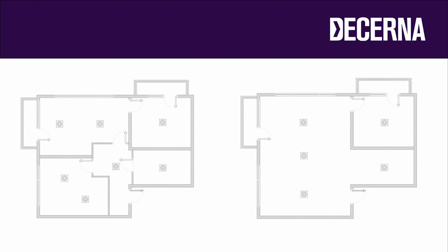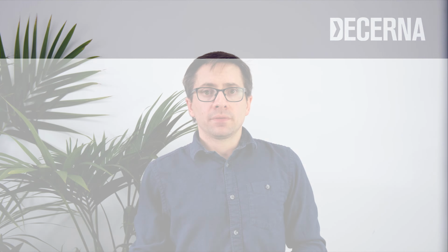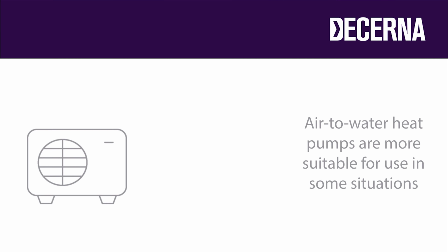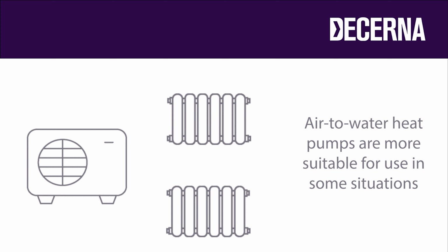Air-to-air heat pumps are usually best suited to sites with large, open-plan spaces, and the number of indoor units for a given floor area can be kept to a minimum. Although there is a high level of controllability from individual indoor units in each room, the costs can quickly mount up. The cost of an indoor heat pump unit is considerably higher than that for a typical radiator. So, for instance, in buildings with a large number of small rooms, it might be worth considering an air-to-water heat pump instead, as their heat is emitted from radiators and therefore might be more cost-effective.